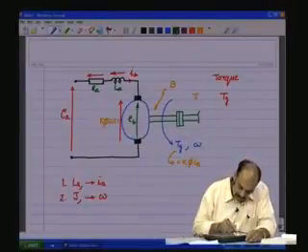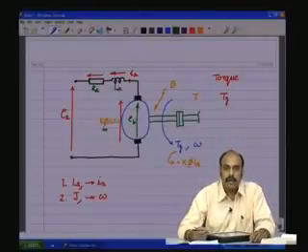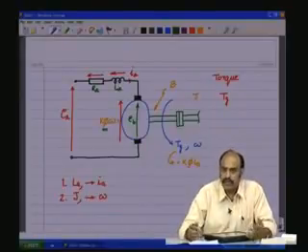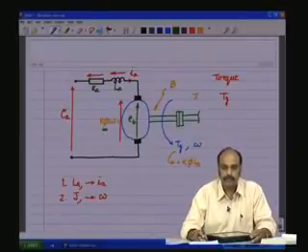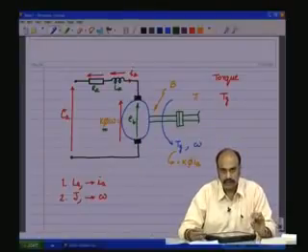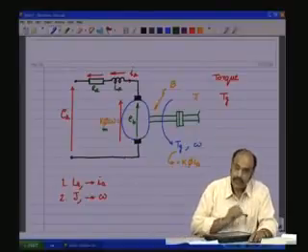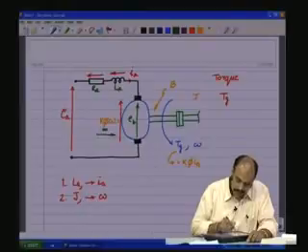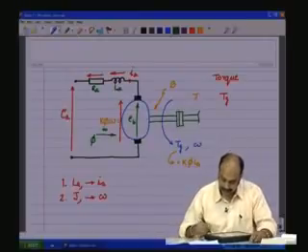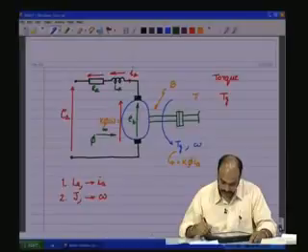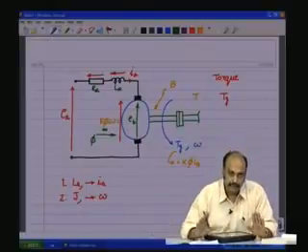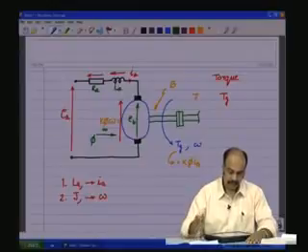Now, there is one more issue, and that is phi. How are we generating phi? Because the excitation, the field, is being generated differently with respect to different topologies of the motor, as we saw in the case of the shunt motor, the series motor, compound motor. The phi is being generated separately. So, which means as far as this motor is concerned, there is one more input which is phi that we need to take care of. So, first let us consider the case of the shunt motor, or a separately excited motor, where phi is a constant. We are not touching phi. So, under that condition,